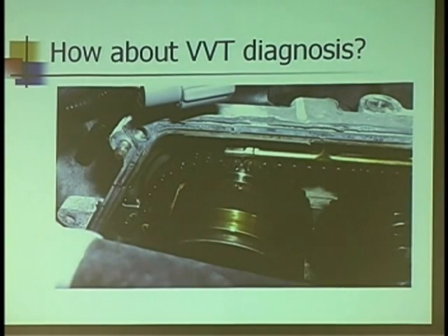What about using it for variable valve timing? Yes, sir. Actually, that was going to be my question. For variable valve timing, if you're revving it up, would that move? It should. Obviously not the spark line, but the other pattern? Yes, you can see that. You'll see the ramp move.